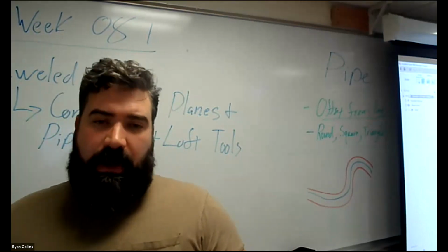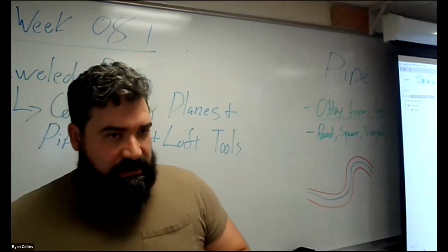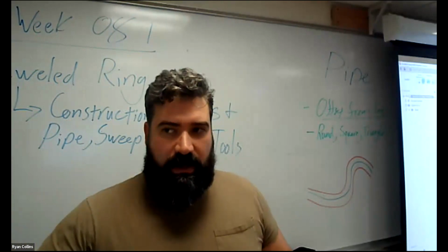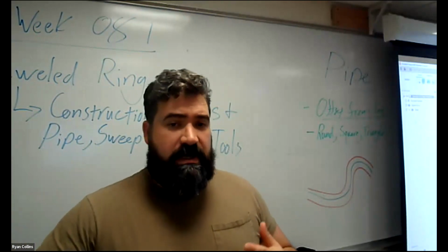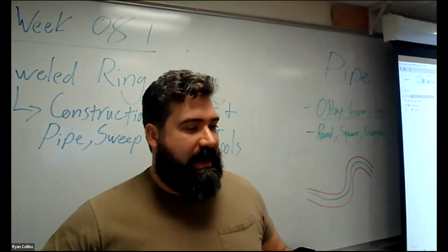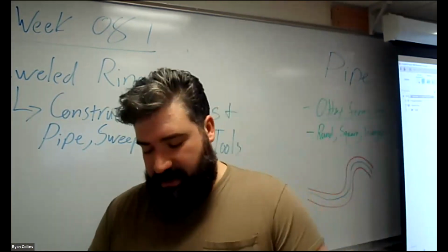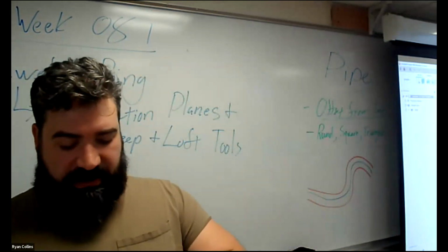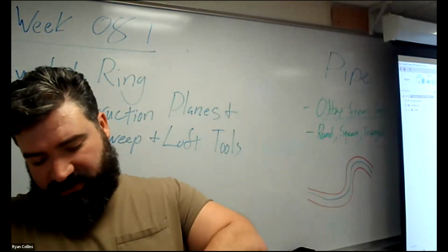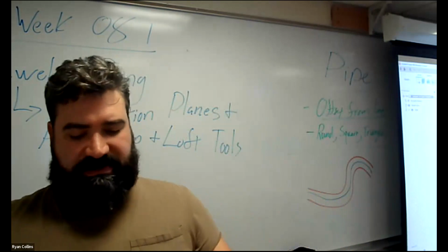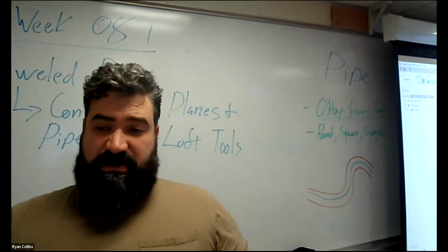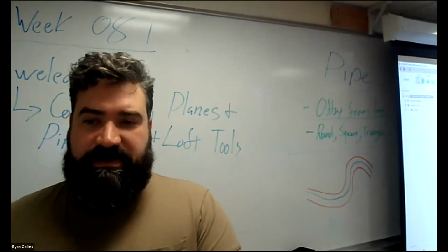So to begin, I'm not going to put my immediate dimensions into any components because I want to keep that outside and still be able to refer to them back and forth. So first things first, like I said, I'm going to take a measurement off of apparently my ring finger, which is rotating around more or less 20 millimeters. Sure, that's about right. All right, so I'm going to start a sketch.